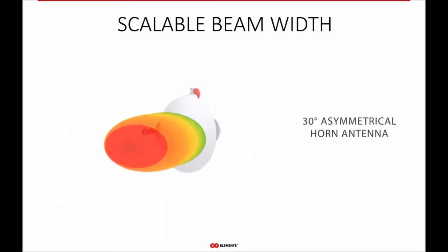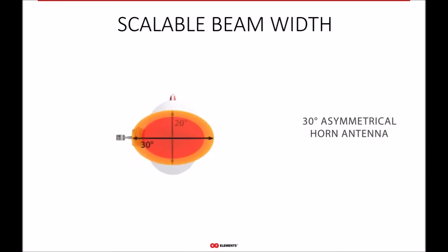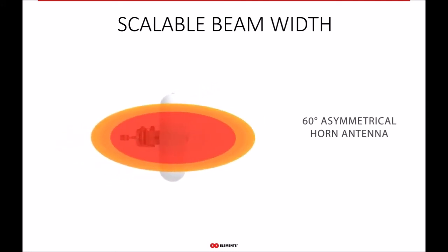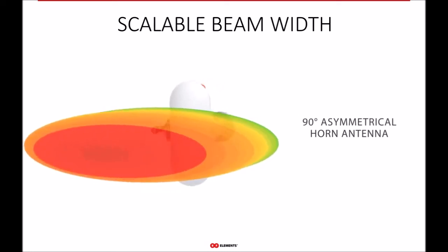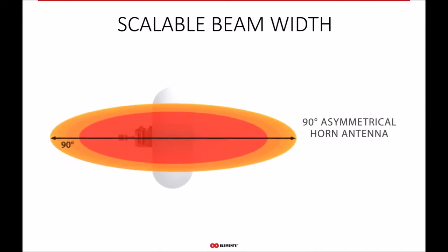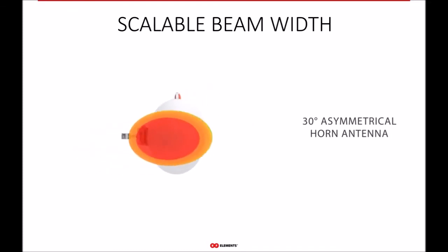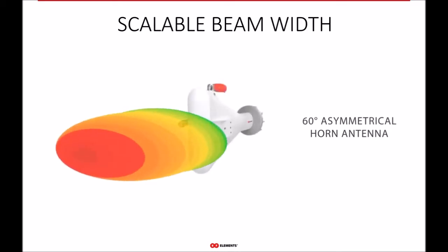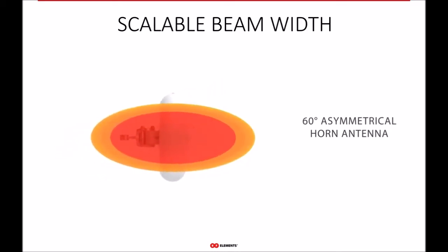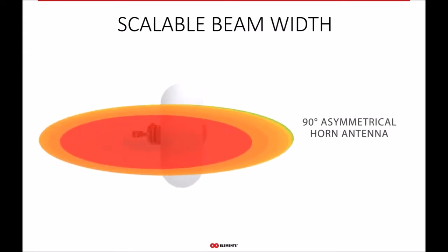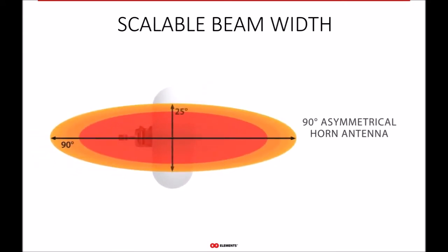Horn technology is so flexible that you can actually choose if you want to change the beam width in both horizontal and vertical planes, or only one of them at a time. When you squeeze the horn only on one side, in this case, we're showing examples when they're squeezed in the horizontal plane, you change the beam width only in the elevation. This results in an asymmetrical beam, which again fits particular scenarios with rather flat landscapes and adds a few decibels of gain so you can cover more distant areas. Yet another tool to your WISP toolbox.